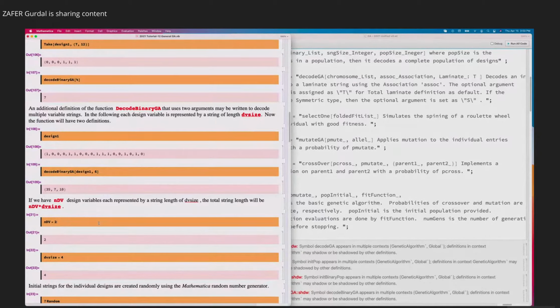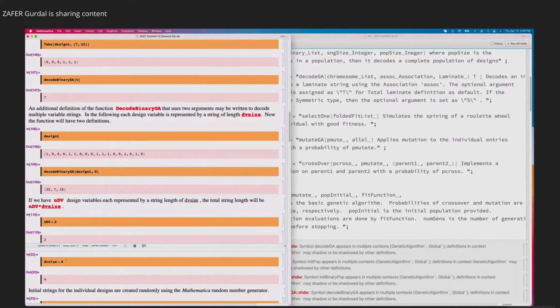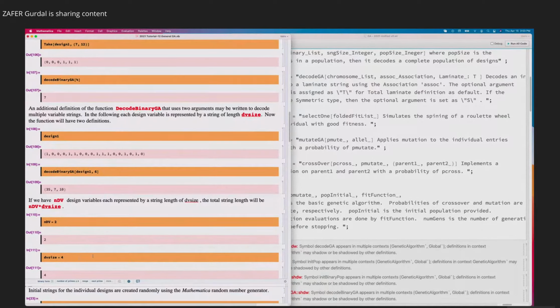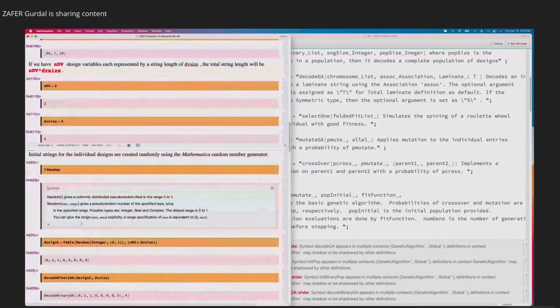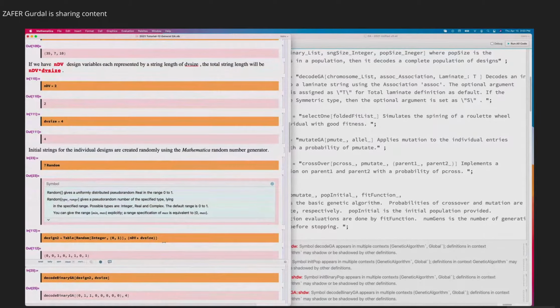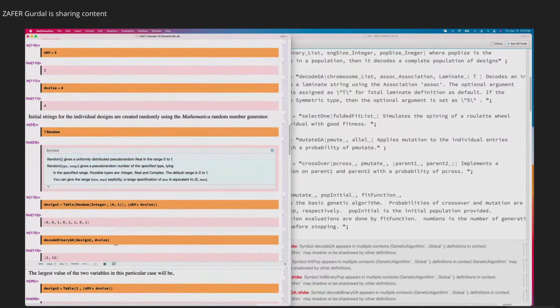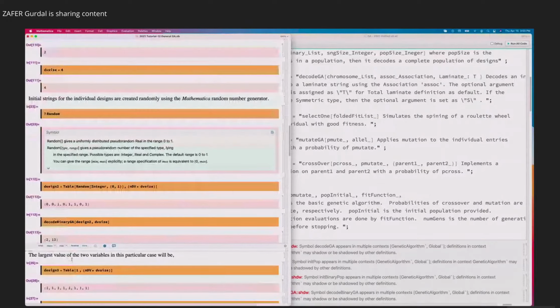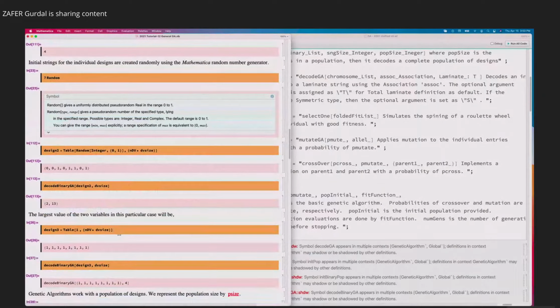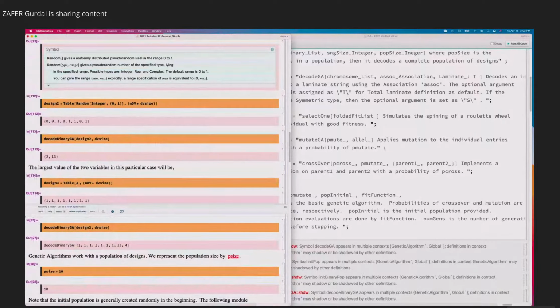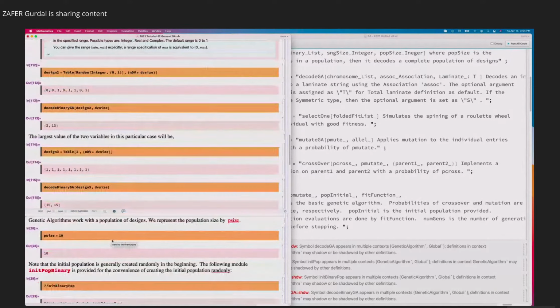So we're switching the problem to a 2 design variable case, and we're representing each variable with 4 digits. And then we use a random number generator to create a second design. Let's say it's this one. And if I decode this design, which is generated randomly, it produces integer engineering values of 2 and 12. And I can again define another design, which is the largest that you can have, by setting all of them to 1. And if I decode this one, it's 15 by 15.